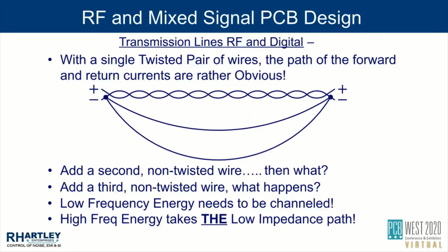At really low frequencies, in order to contain the low frequency fields, it may be necessary to split the ground plane. But we haven't even done it in circuits I've worked on, even at low frequencies. We've located the low frequency analog components, so there was very little risk of the energy drifting away from where we wanted it to travel, and then we didn't have to worry about it.